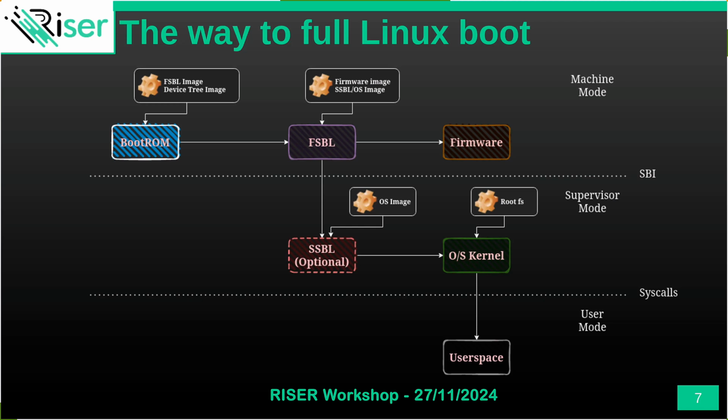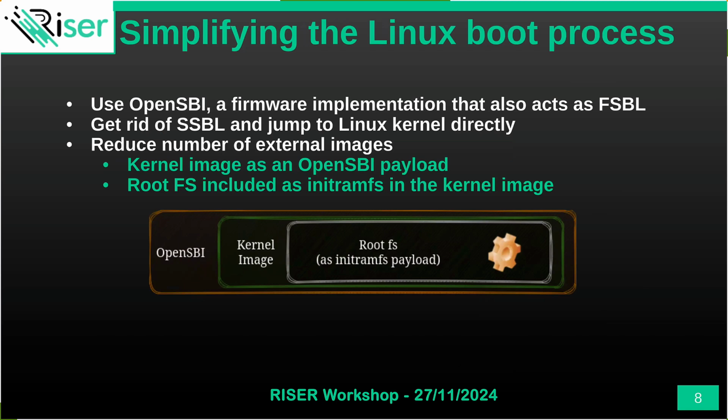The more you advance in the boot chain, the more complex the software becomes. And finally, you have the kernel. Now the kernel also needs to fetch the rootfs from somewhere, usually from storage, in our case from network most of the time, because we don't have storage in our FPGA prototype, so we do a lot of stuff with NFS there. This is a complex process, and if you are debugging, you don't want a complex process. You want the process to be as simple as possible so that you don't have a lot of noise there.